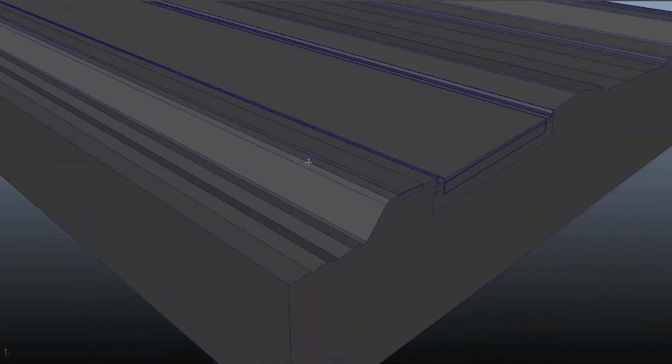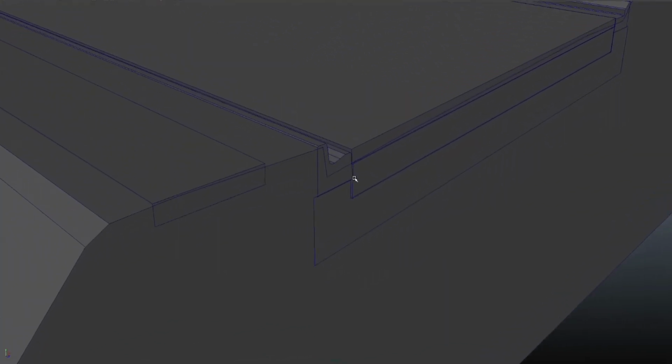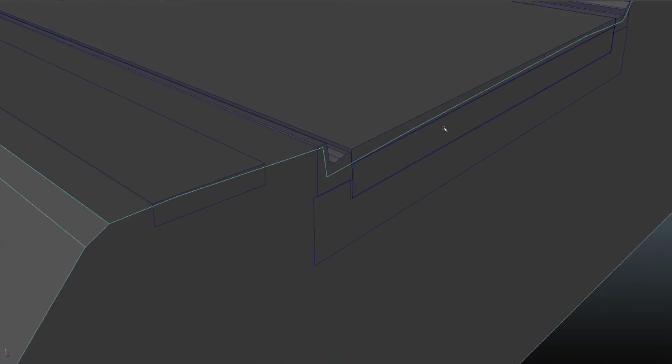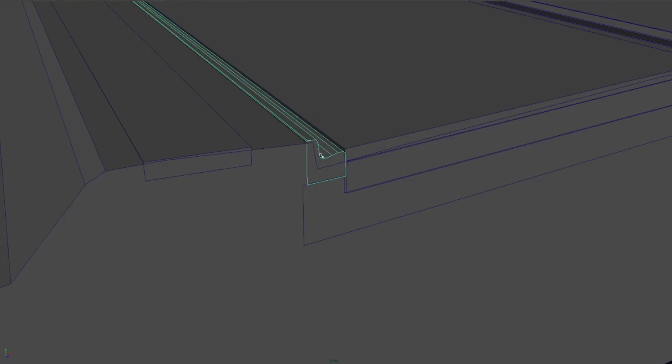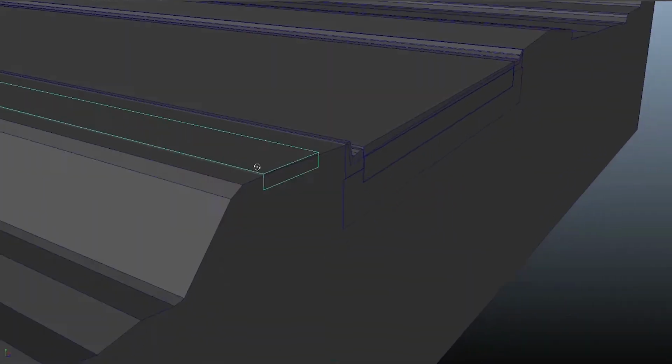One thing we're going to want to do right now is this: everything is coplanar. So in other words, we created all of these shapes and all these polys at ground zero. So when you render this, you may not be able to see the difference between the curb and gutter, the stabilizer, the road, and the sidewalk because all their edges are lined up perfectly with each other. See that on the side there?